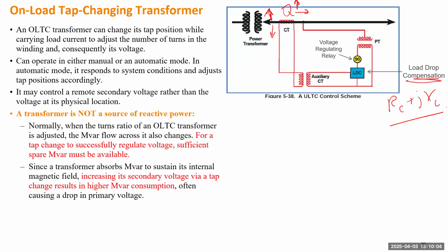When you design this negative feedback control, you determine moving up will bring more Q to the secondary side and then support voltage. So you just keep that same direction. But if the primary side is very weak and the Q cannot increase, like the primary side almost reaches a limit, but the tap doesn't know, it will keep moving. It can go the opposite way.